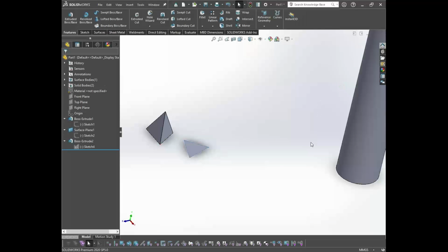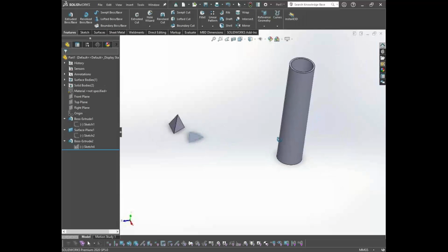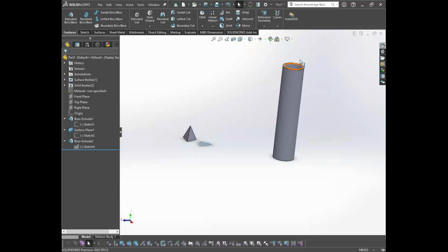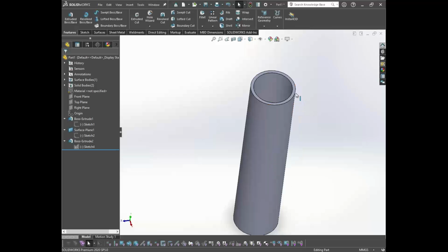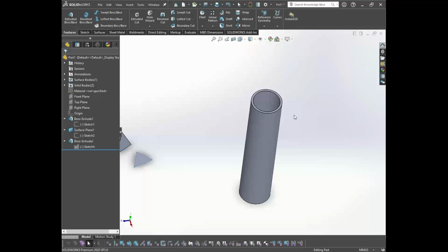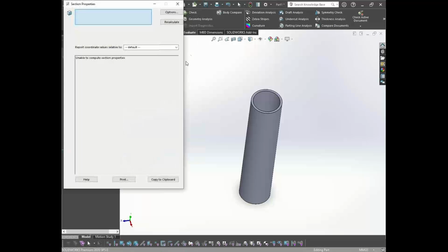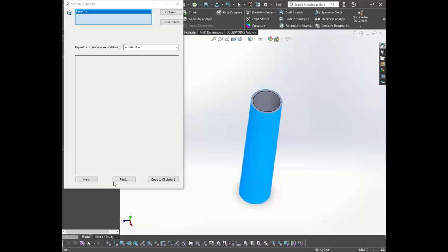Okay, the figure we failed to save, but I have drawn a single line. When I import it into SolidWorks Simulation, it will simply be shown as a single line and two nodes at the end. It won't consider the 3D geometrical or graphical interface of this shape. In the backend, the solver will consider all the sectional properties involved. It may be the moment of inertia, or if we simply go to evaluate and check the section properties of this particular thing, we can calculate.